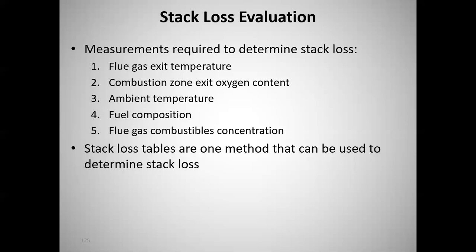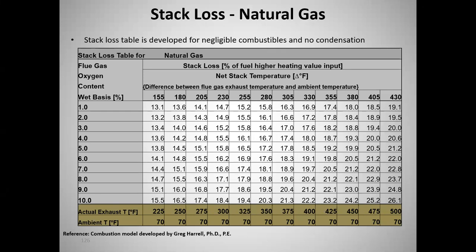So how can we actually do this? Well, there's a couple of ways. It turns out to be pretty simple. There are online calculators, and Measure has a stack loss calculator in it, and I'll pull that up here in just a second. And we also have stack loss tables that are published for different fuels. So we'll go through both of those methods. So this is a stack loss table for natural gas.